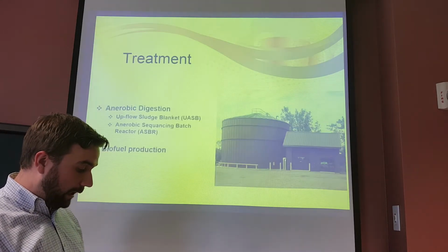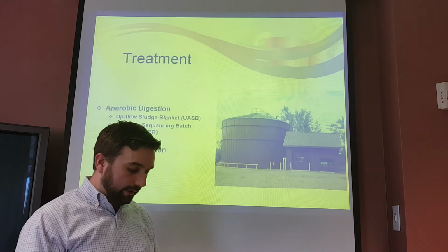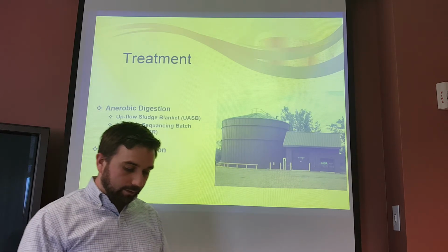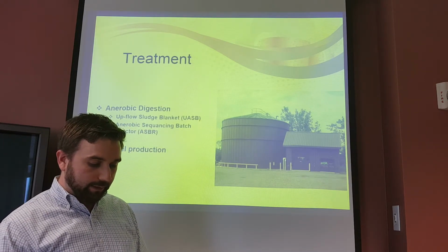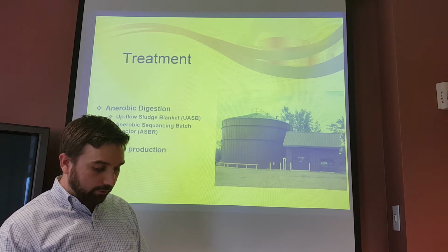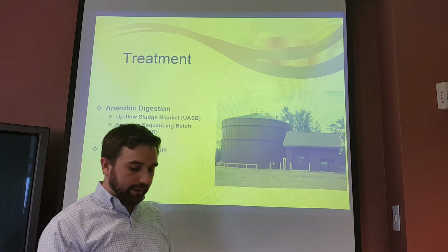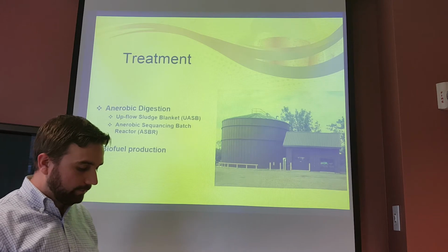Anaerobic treatment is becoming more popular due to the possibility of harnessing and reusing biogas to offset some of the operating costs. There are many types of anaerobic treatment configurations. Most common and most applicable for breweries would be the upflow sludge blanket and the anaerobic sequencing batch reactors.